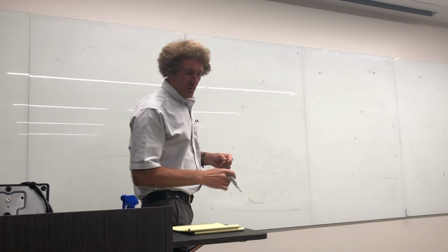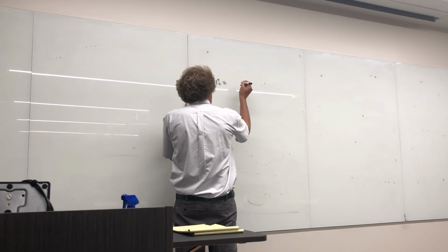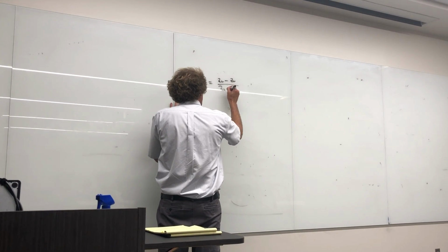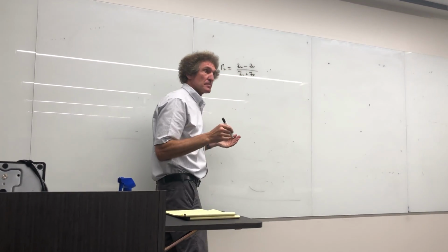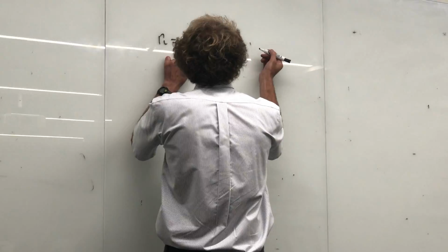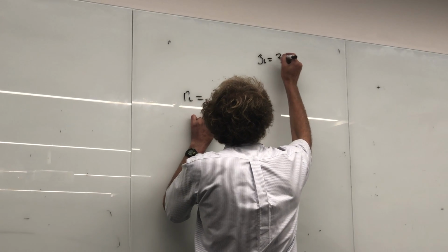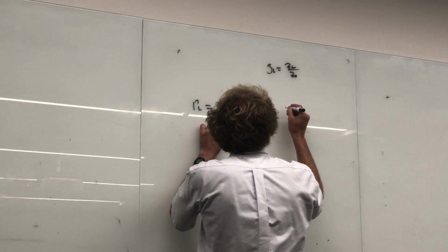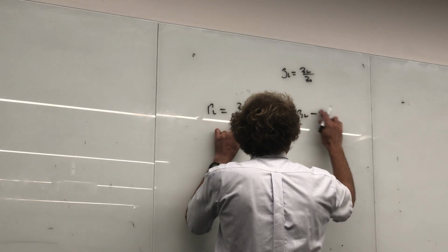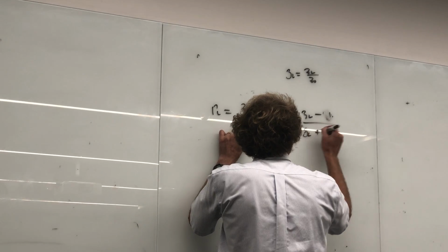When we start and we talk about reflection coefficient, it's equal to ZL minus Z0 over ZL plus Z0, right? If we divide top and bottom by Z0 on this equation, we would get something we call small zL, which will be equal to ZL over Z0. So that would be small zL minus 1, pardon me, over small zL plus 1.